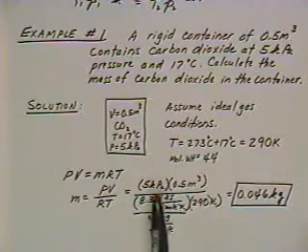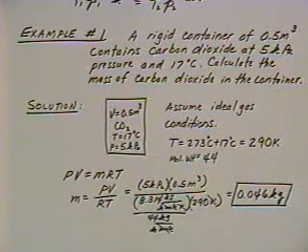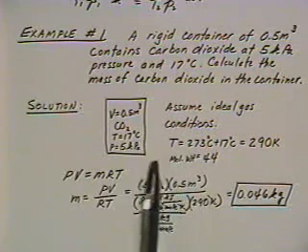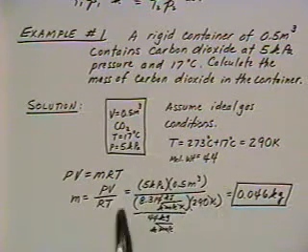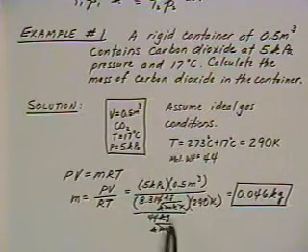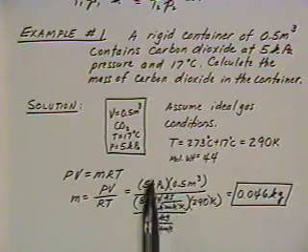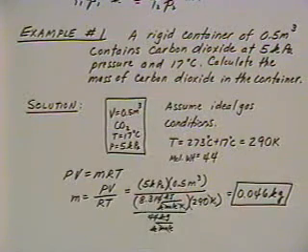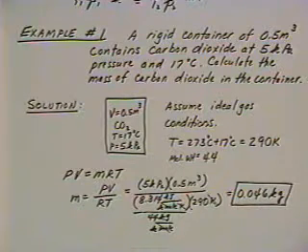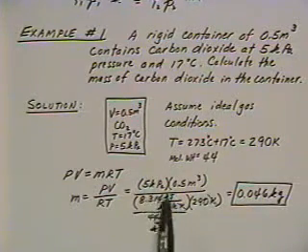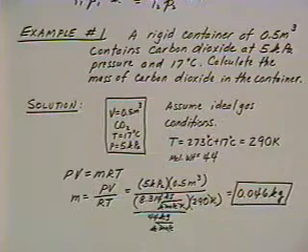Sometimes I've included the units in the problems. If it's a repetitive set of units, I haven't included them, but again, a recommendation is to go through the units and make sure they're compatible. For instance, you've got kilopascals up here and kilojoules here, and so when they're both in the same set of units, then you don't have to worry about that factor of 1,000 that sometimes enters into it if one is in pascals and the other is in kilojoules. So make sure your units are always compatible when you go through.